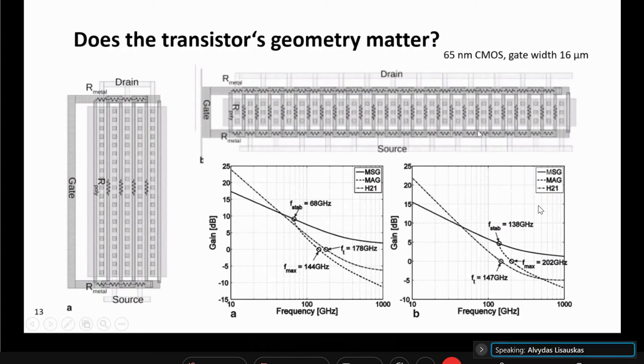And now if you take the top side, Fmax is lower than Ft. That's one thing one has to see: at the left side, and the top side, Ft is lower than Fmax. So one can get really different high frequency performance of the transistor, and this is another part of art when one designs high frequency oscillators here.